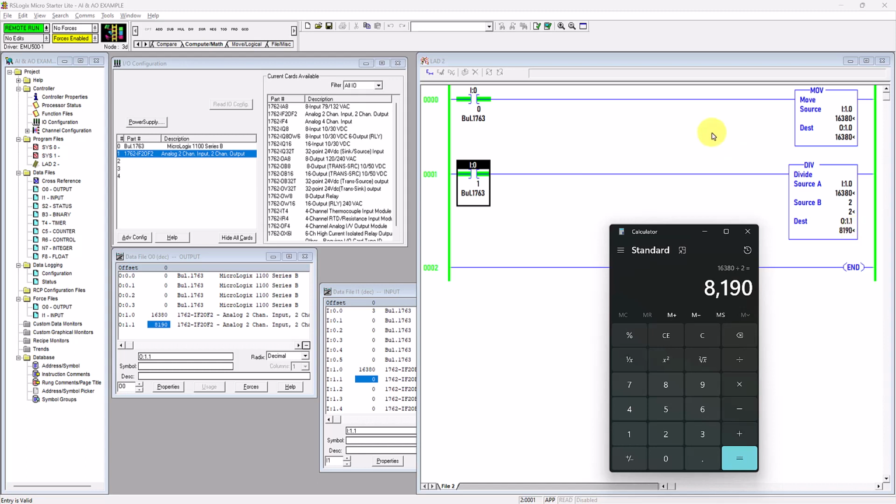So when you connect the multimeter to this analog input output card module, and then you measure the voltage at this channel 0, you will get the voltage of about 5 volt. Yeah, 5 volt, because 16380 is the half of 32760 digital value or PLC digital input data range. So we get about 5 volt.